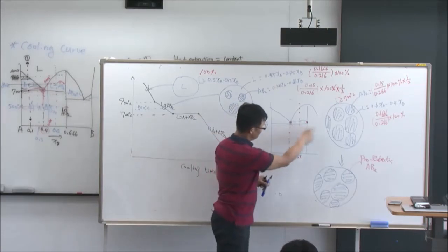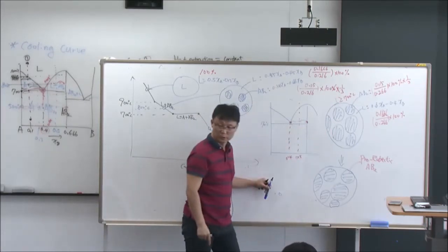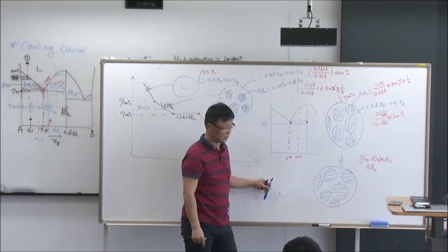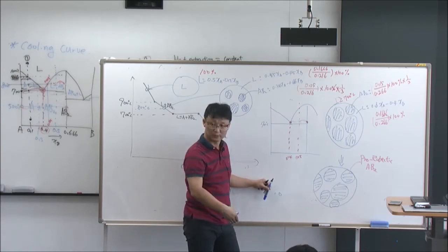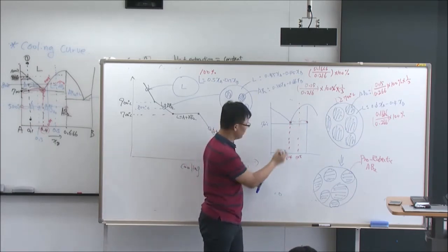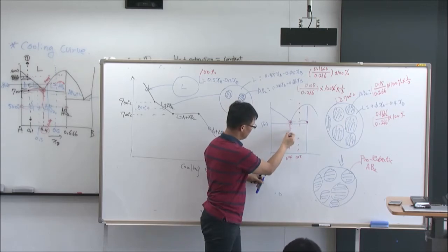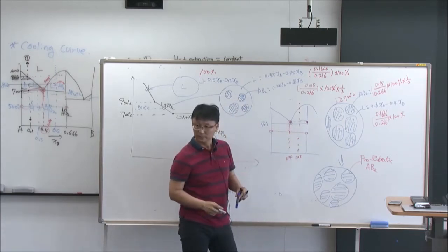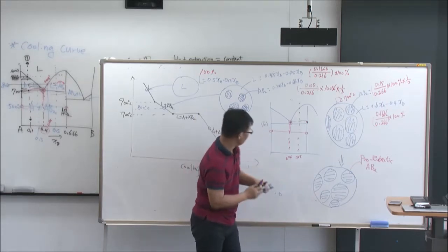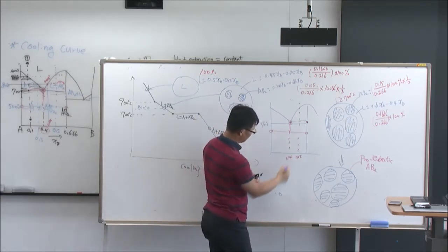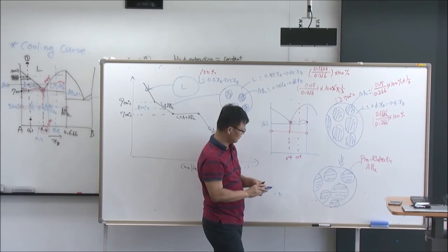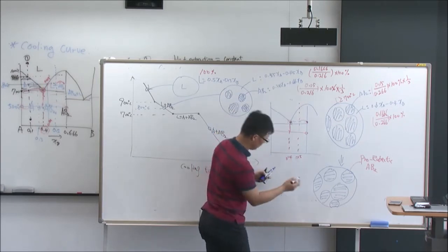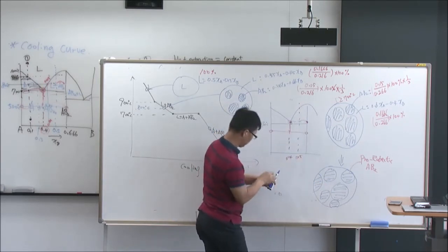And then the liquid which was in between this eutectic AB2 phase starts to cool down by itself and starts making the solid phase. So the liquid was this one and it cooled down, it formed this solid and this solid phase. That actually should be here. So it will form A and AB2. Yeah. So A and AB2.